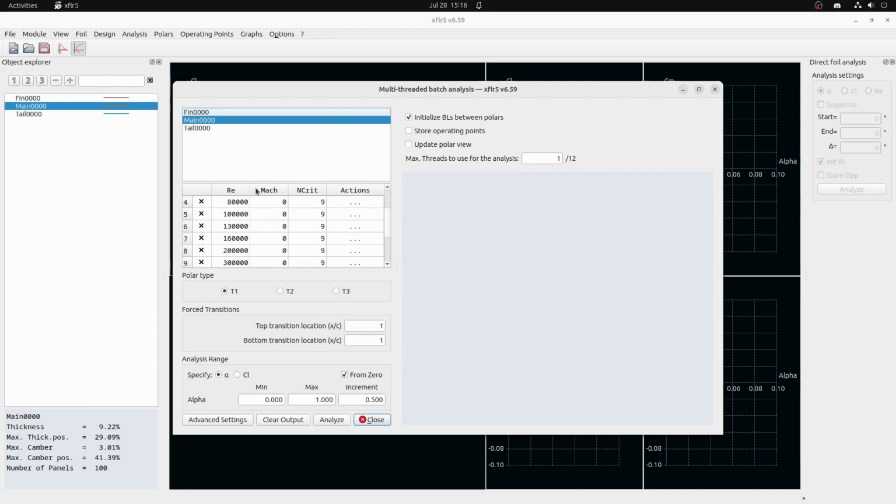The Reynolds number for an airfoil is large if the aircraft's moving fast and for large areas of wing, and it's small, of course, for smaller sections of wing and for slower flying. I'm not sure this range will cover everything perfectly. 30,000 isn't particularly small, so I'll just do a small amount of editing and I'll try and cover the smaller Reynolds numbers for this sort of aircraft.